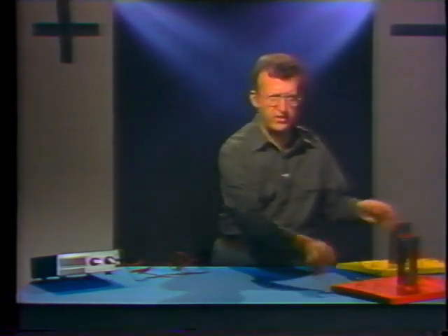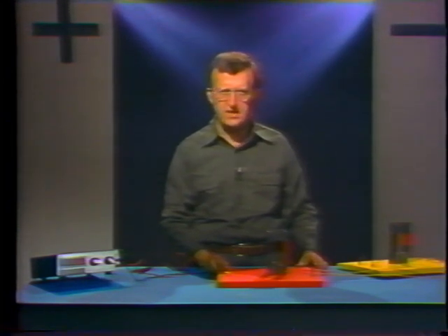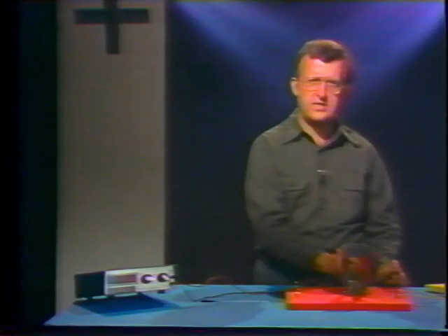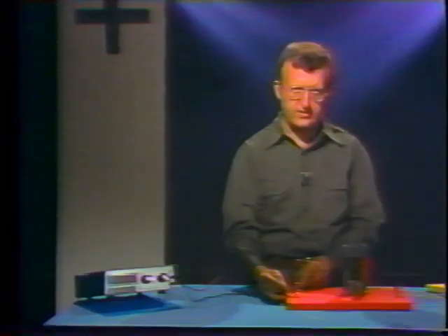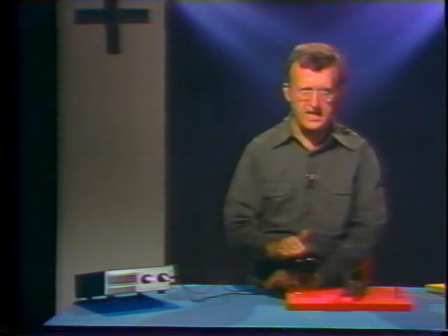Now, the reverse of what we just saw is also true. If there are fewer turns in the secondary winding than in the primary winding, the primary's magnetic field will have fewer conductors to cut across. The induced voltage will be less than the applied voltage. This time, I have a coil with 50 turns for the primary winding and a coil with 25 turns for the secondary winding. The voltmeter will read 6 volts for the primary, and since I have fewer turns in the secondary winding, I can expect the secondary reading to be smaller than the primary reading, and it is. It's 3 volts. In this case, with fewer secondary turns, the transformer decreased or stepped down the voltage.